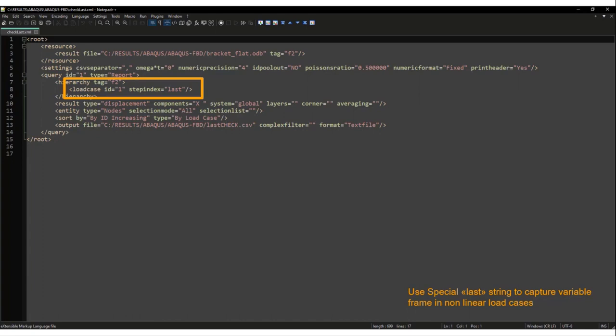In the past, the results query was hard coding the simulation step on a specific ID. So let's assume you have run one where your simulation step is the 10th frame, the last one. And then you want to apply the same query on a next run. Then for whatever the reason, the last step is simulation index 12.